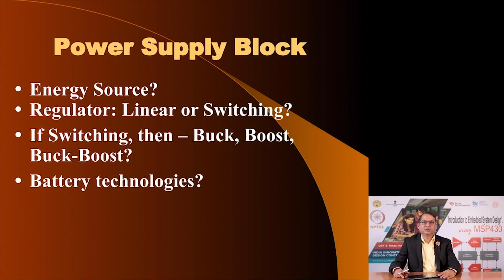Are you going to need batteries in your application because the input source is sporadic and your system wants to operate during those times where the input energy may not be available, and therefore you create a battery backup? Or are you going to use a supercapacitor to store energy during times when the main source of energy is not available? All these considerations go into the design of the power supply block.